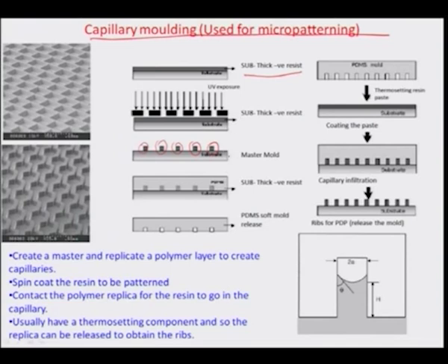And basically what you do is you take this mold and create a negative replica by using PDMS, and create a replica of small cavities on the lower surface like this, at a resolution achieved by SU8 and the UV exposure driven photolithography.